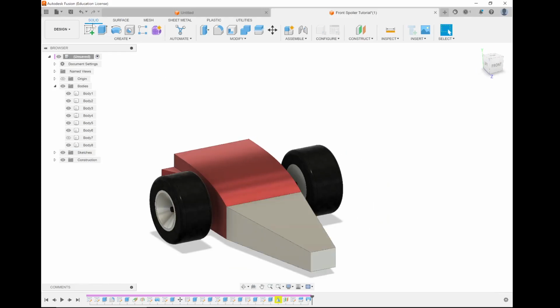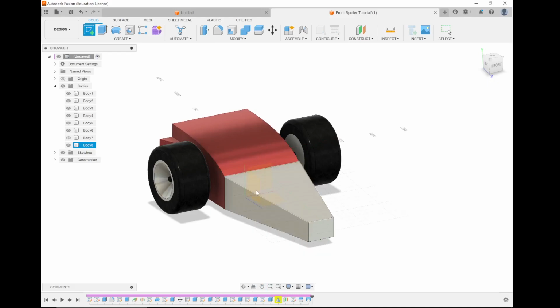So now we're going to make the horizontal wings. We will press the sketch tool. We want to press this plane over here where my mouse is hovering. If you hold, so right now I'm holding the left mouse button, when you do that, it opens up this table. What this is saying is your mouse is hovering over multiple elements in your drawing. So if you hold the left mouse button, you'll get this little table, and then it lets you select which actual element you wanted by highlighting that particular element.